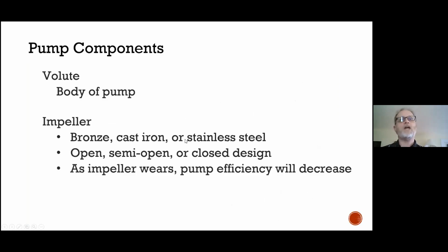All right. So key components for the exam, obviously the volute. And remember, the volute is that portion of the pump that converts the high speed that's imparted by the impeller, the kinetic energy, which is the speed or the velocity of that moving fluid, water, and converts it to pressure energy. So the impeller creates the velocity, the volute converts velocity to pressure. And we saw in the video 3 styles of impeller: open, semi-open, or closed. And again, based on the type of fluid and how much energy we're trying to impart into the water column.